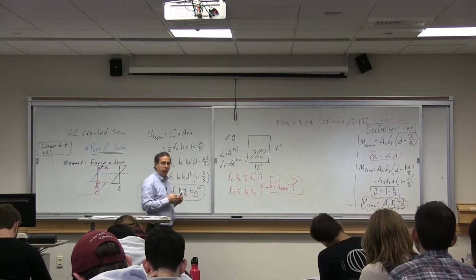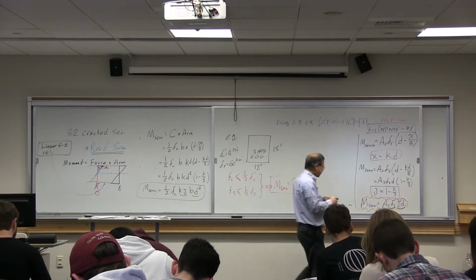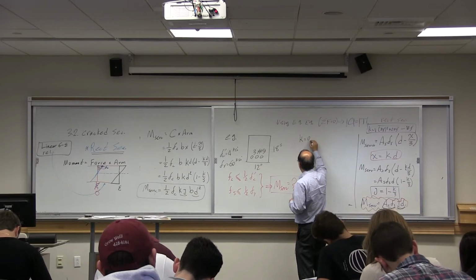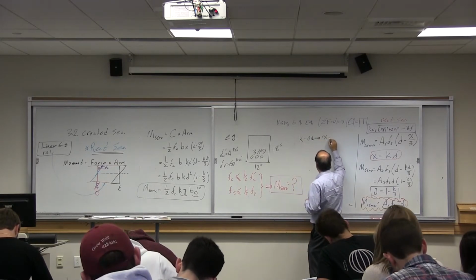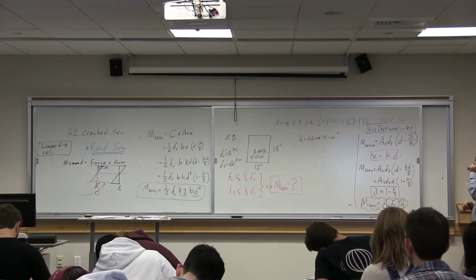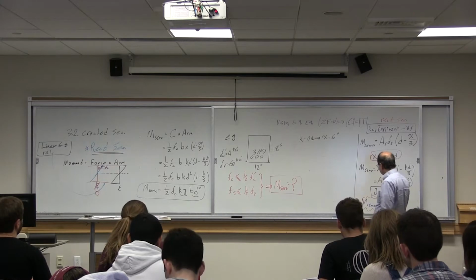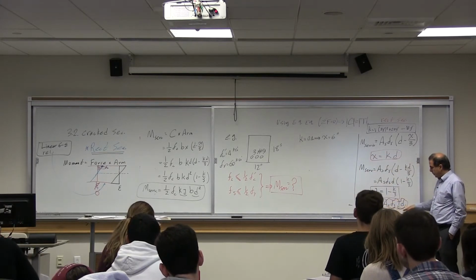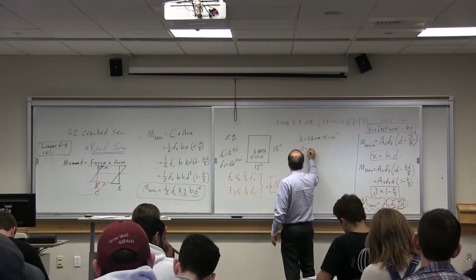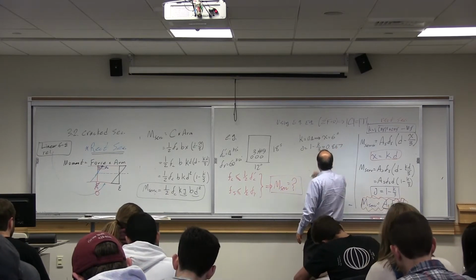what is M service? We have calculated K from before. K was 0.4. Therefore, X was 6 inches. We did it last time. If we want to use this relationship for rebars, we need to calculate J. J is 1 minus K divided by 3, which is 0.867.